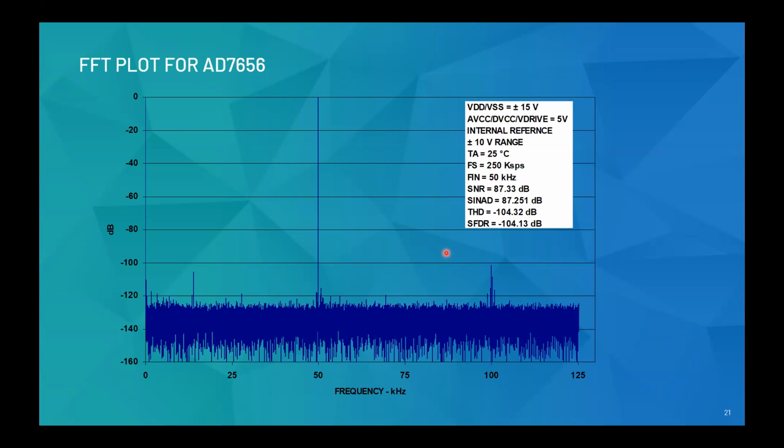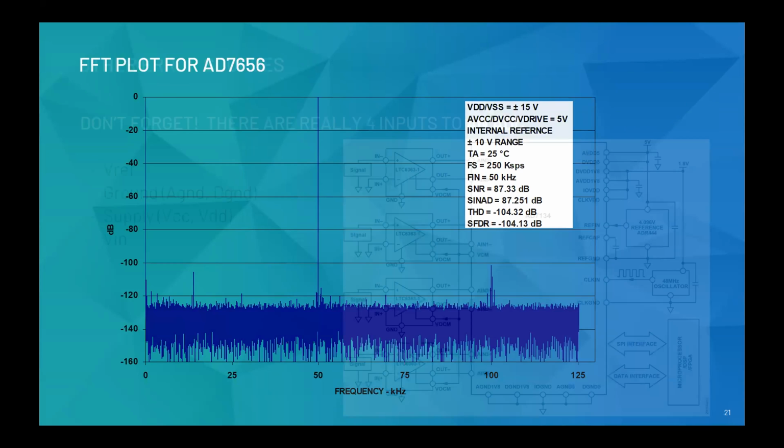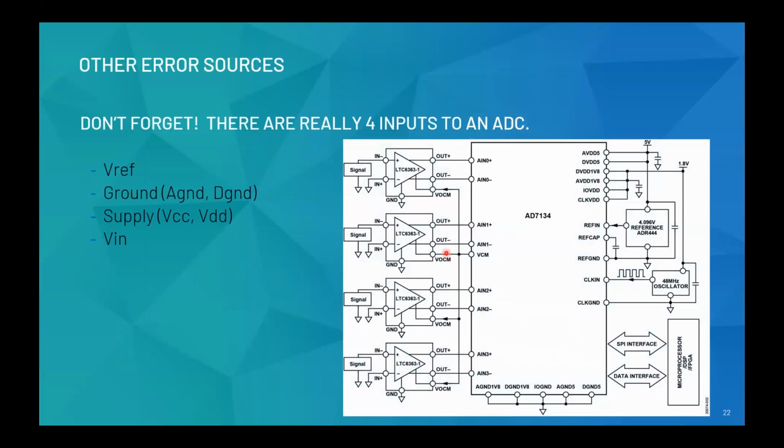All right, so we have covered the AC and DC specifications. Now, before going into ADC architectures, I would just say that every ADC has 4 types of inputs. It's not only your analog input. There are other things like reference. Reference is something your signal is always getting compared to and calculated against.